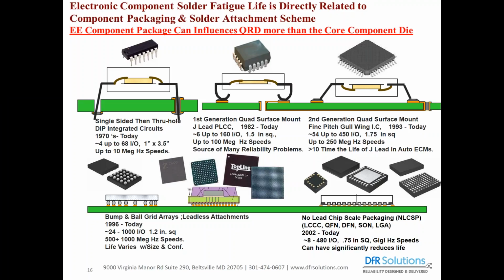The IEEE put together what they called a compliancy task force to look at the issues of stiff leads fatiguing themselves out of these little solder joints, and that led to the development of a second generation of surface mount electronics, with what was known as the fine pitch gull wing lead. So here we have a lead with two bend points, and those bend points basically allowed the component and the circuit board to move relative to each other.